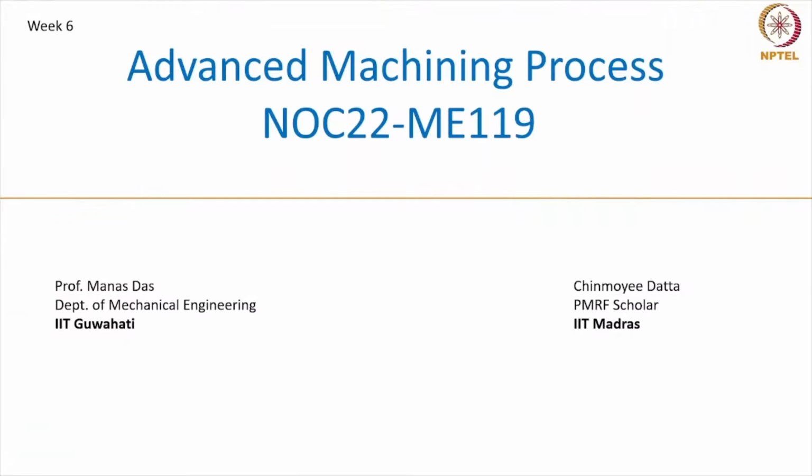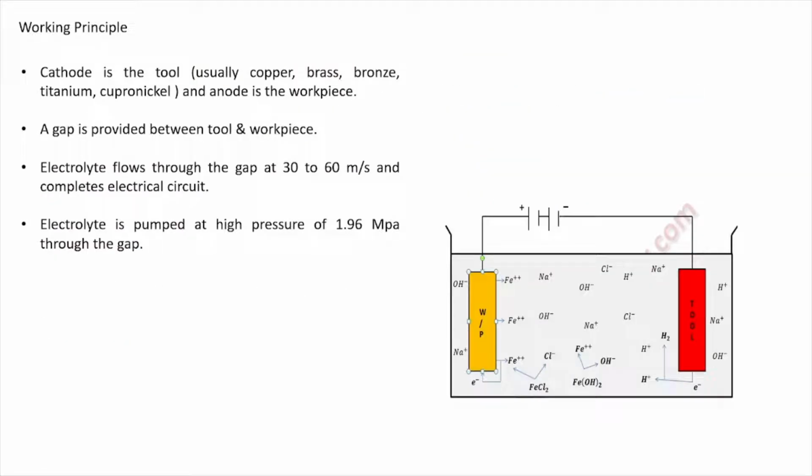Yeah. So here we are seeing that the workpiece and tool are acting as anode and cathode, and if we take the example of the low carbon steel machining process, low carbon steel is made up of a ferrous alloy, that is iron. For the electrochemical machining of that steel, mainly a neutral salt solution, or sodium chloride solution, can be used as the electrolyte.